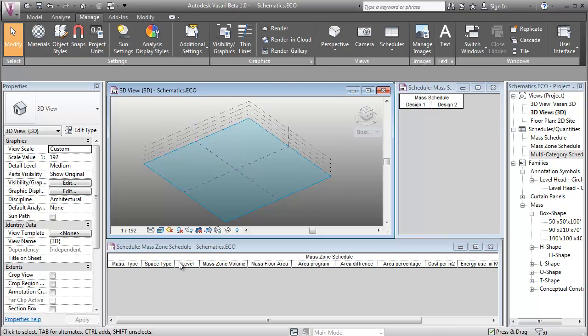And then to set up a schedule with some different shared parameters and some project parameters, and to make some calculated values and to use yes and no parameters to validate that we have the right square meters in relation to the overall program, and to set in things that we might get out of energy simulations in the conceptual energy analysis or from another tool.